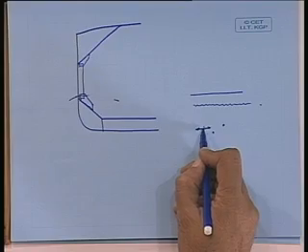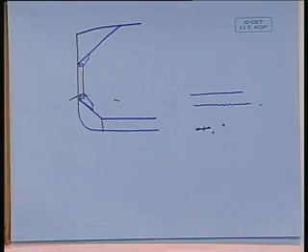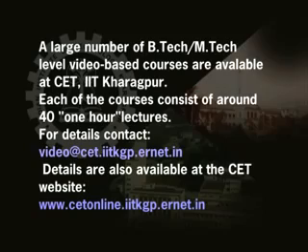It is a small circular hole on the surface, and on the surface whatever is the fiber stress, you can expect that on this side it is 3 times that. And if that is the stress value, you are likely to have a failure here, a hair crack or hairline crack.